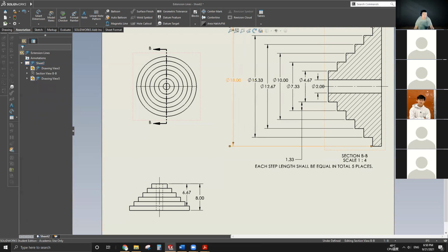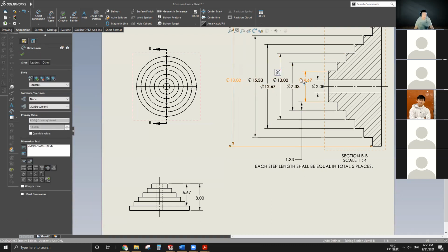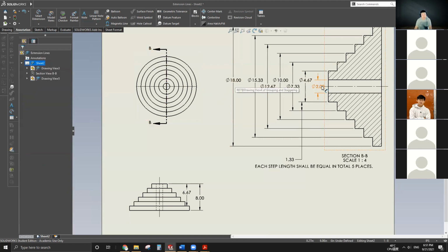And with this OD diameter, you can get rid of all the diameters in between. And if this bore is very critical to you, you can leave this on there as well. So it will be a trade-off. You have a well-controlled outer diameter and a well-controlled bore, and you lose the control of each individual round surface in between. So do you guys understand what I'm talking about?